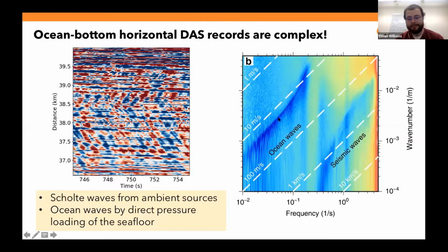And it's becoming increasingly popular in onshore surface wave analysis to not just strictly apply techniques to the passive data set like MASW as it was originally envisioned by Park, but to apply ambient noise interferometry first, the principle being that you can cross-correlate wave field measurements at 2 discrete locations and extract something that approximates the elastic Green's function between them. And therefore, you can organize the wave field, rendering it much more simply suited to separating different phases